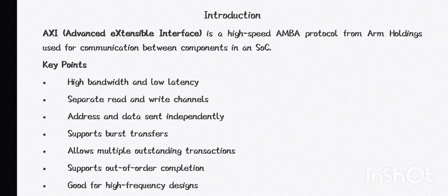Key features of the AXI protocol are: separate address, control and data phases; support for unaligned data transfers using byte strobes; bus-based transactions with only the start address issued; separate read and write data channels that can provide low-cost direct memory access; support for issuing multiple outstanding addresses; support for out of order transaction completion. It also permits easy addition of register stages to provide timing closure.